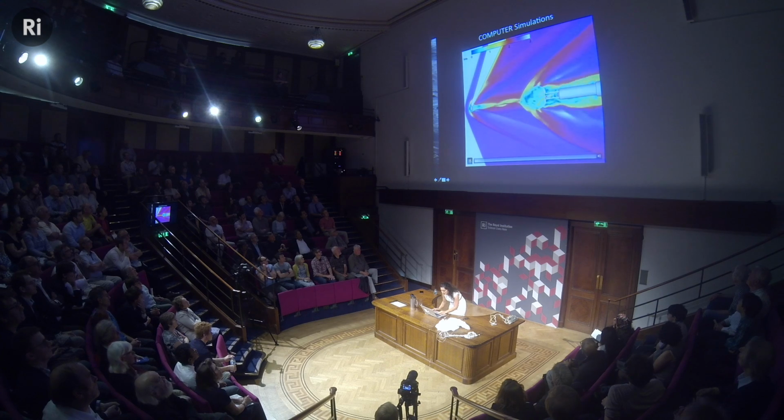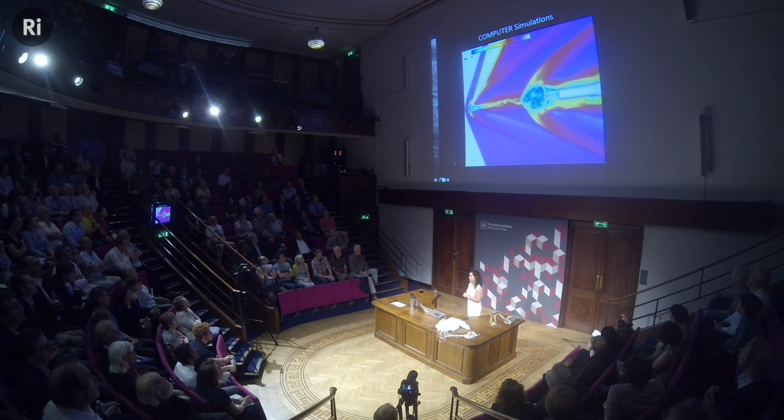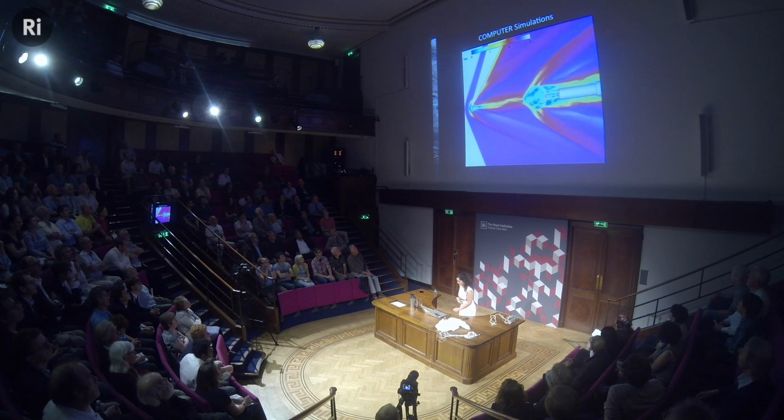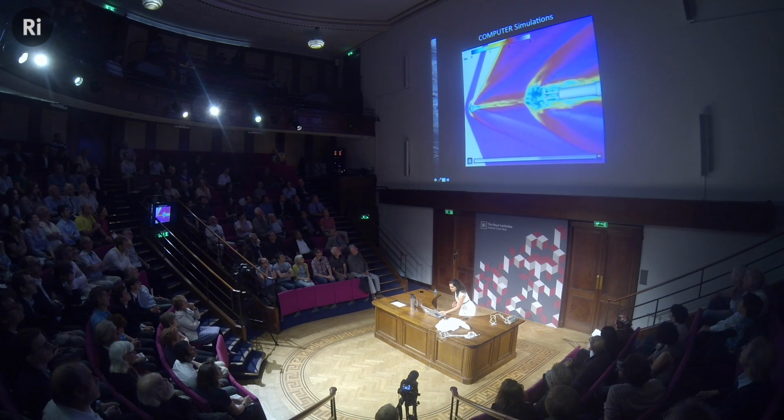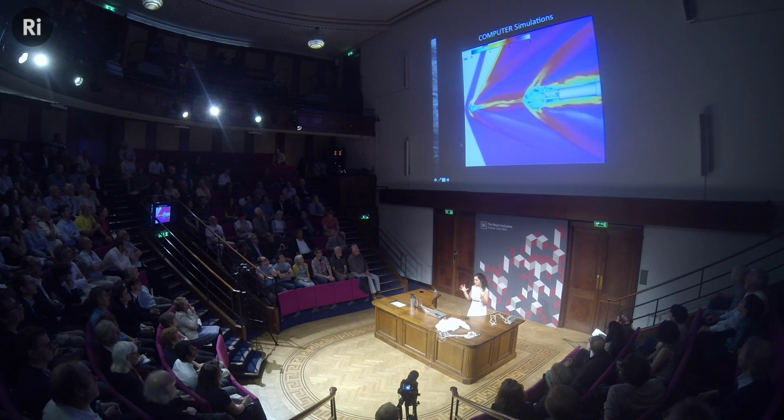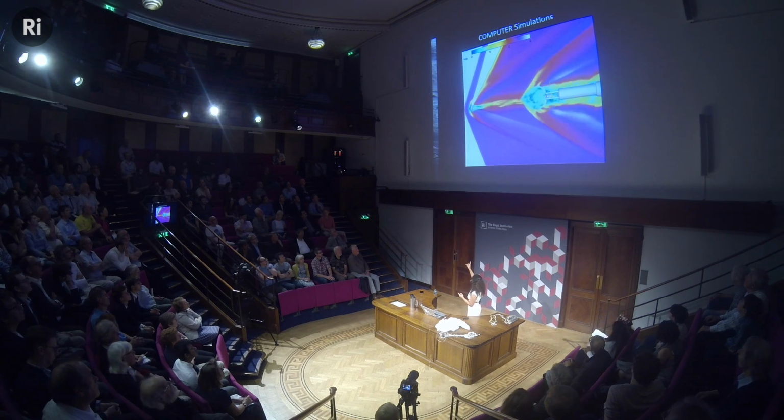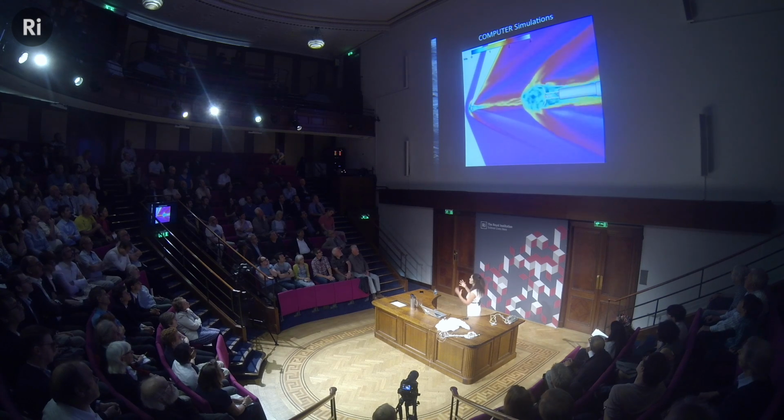And so we first started off with a computer simulation. This is something called computational fluid dynamics, where we represent the flow field around the vehicle. So the MSL vehicle is basically here, and trailing behind it is the parachute. What you see in front of this is a bow shock. This is because we're in supersonic flow. And so we generated a simulation to understand how the flow field of this entry vehicle would affect the parachute, and then what the pressure distribution would be like, how much load it would experience.